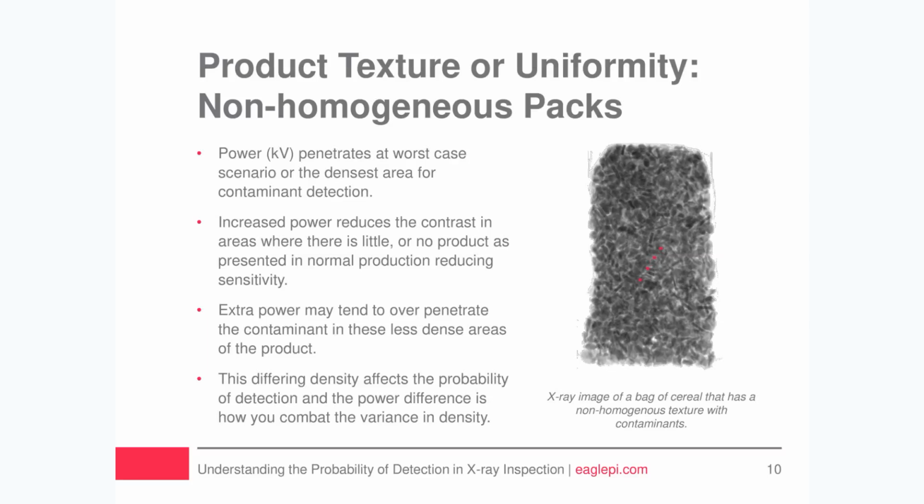of energy. When a product passes through an X-ray system, the detector produces an array of successive scan lines of density information that replicate the amount of energy absorbed, and a grayscale image is created. The system then analyzes that image on what it has been programmed to identify and subsequently reject.